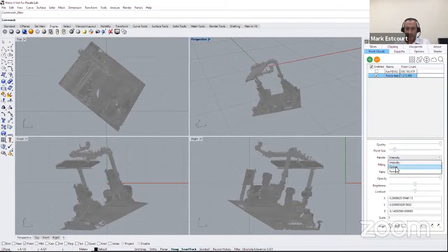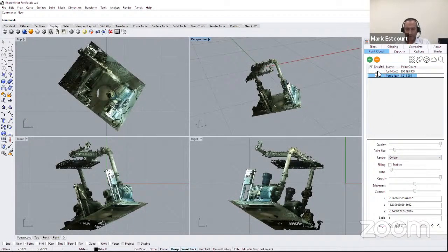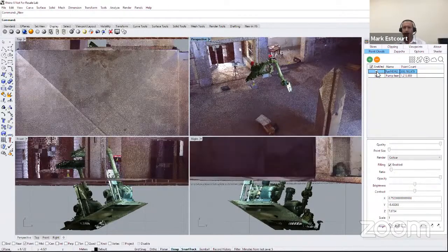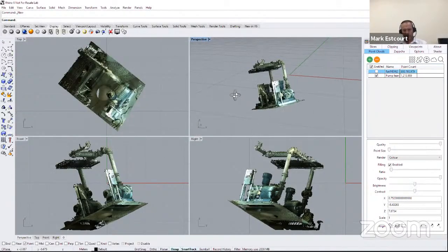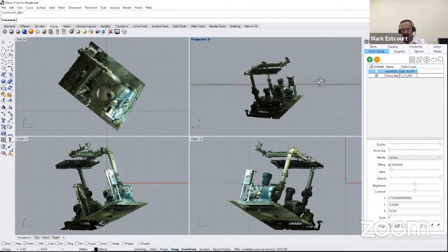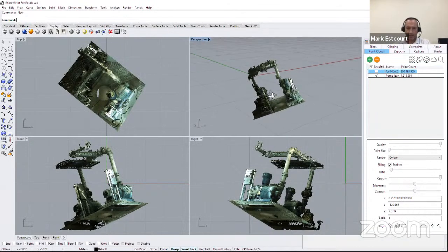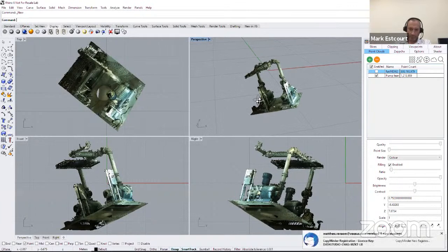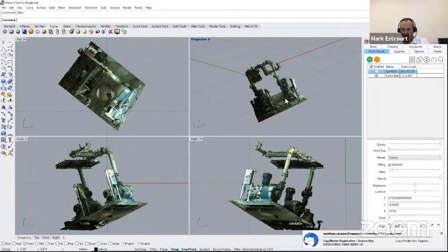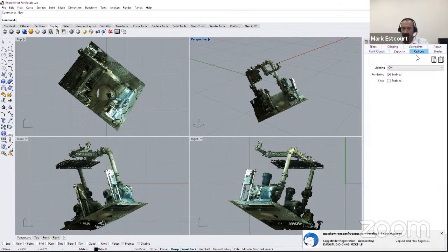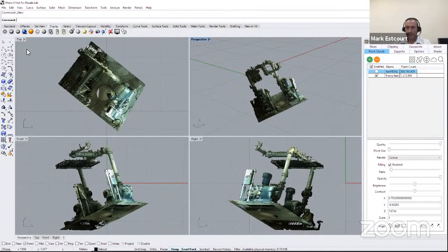What it looks like has happened with this point cloud, which is really worth bringing out now, is that it's not sitting on the plane that you're working on. It's actually on a slant. So what we can do in the point cloud functions is click on the horizontal plane using a Rhino line. Matt's just going to choose the horizontal plane here using a standard Rhino polyline.